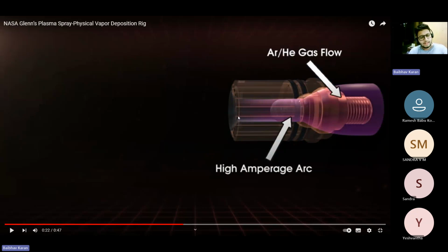Sometimes when you create a high vacuum too, there is a chance of the presence of a small amount, literally a small amount, of oxygen. And because the materials have a high surface to volume ratio, these materials will react with oxygen to produce oxides. If these oxides are deposited on the substrate, they are not pure. This may create porosity in the particle. But we want the material to be pure from oxides.